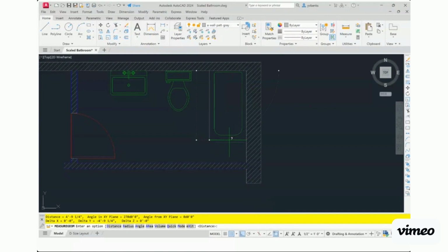Well, we need this tub to fit into this space here that has been designed for a standard soaking tub or just a standard tub. So a standard tub has a length of 60 inches and at least 30 inches wide. A soaking tub is more between 60 to 72 inches long, and it's about 14 inches deeper than a standard tub.